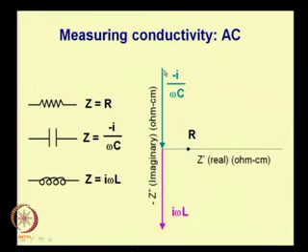For a capacitor, the arrow now indicates the direction of increasing frequency. At very low frequencies you have very high impedance. As you keep increasing the frequency, you get a series of points representing the impedance of the capacitor, which move closer and closer to the origin. All of these points lie along the vertical axis, which is the imaginary axis. At very high frequencies it goes to 0.